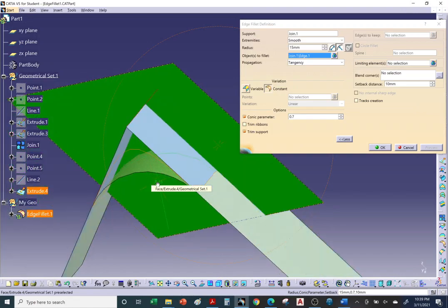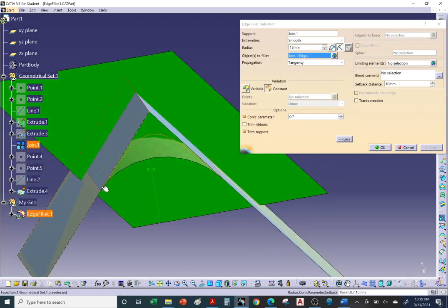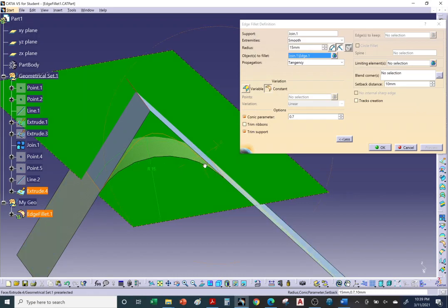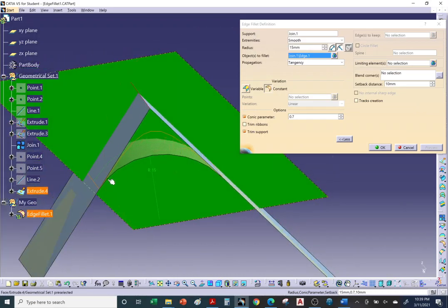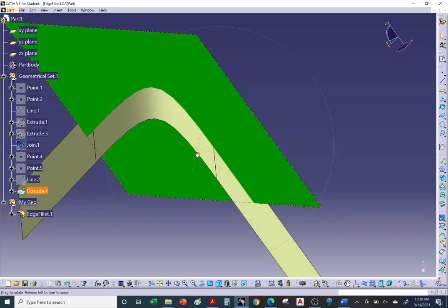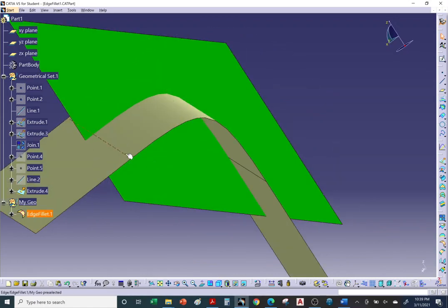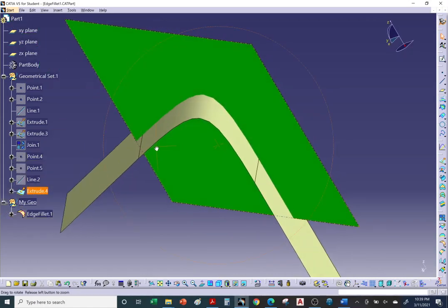Okay, so this helps with styling. So if you work in an automotive studio department, one thing that's ugly is a circular fillet. They'll tell you clean it up, style it. When they mean style it, they want you to use a parabolic or maybe a hyperbolic shape. That way it's hard to tell where the tangency starts. So if we leave it like this, 0.7 hyperbolic and OK. If we don't have this line, it'll be tougher to tell where the fillet starts. It's just a smoother transition.